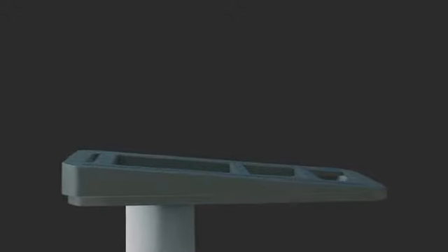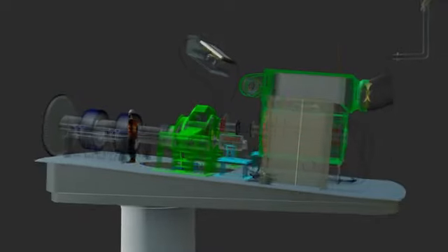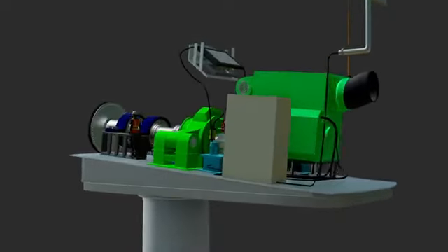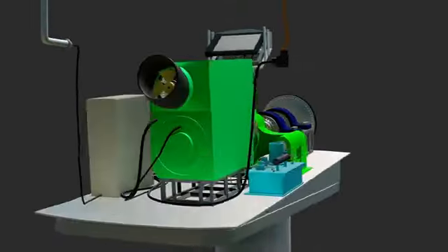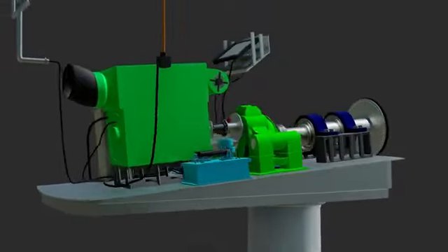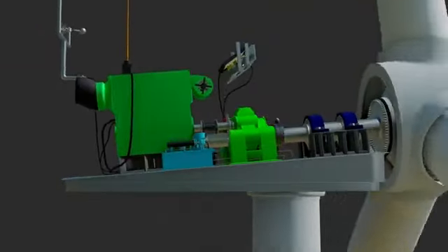The bottom of the bed plate is flat and horizontal. The top surface, where the main shaft and gearbox sit, is machined at an incline. When you bolt the main bearing and gearbox to the bed plate, they automatically point slightly upward. This avoids the need for complex bent shafts. The components are straight, but the table they sit on is slanted.